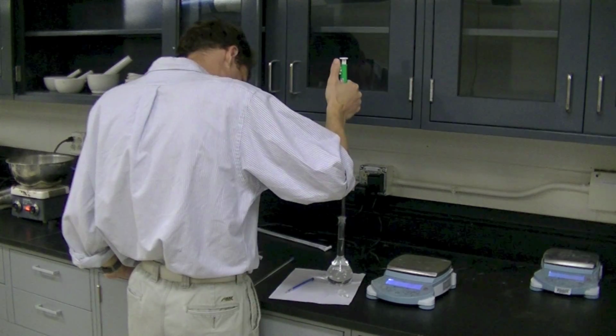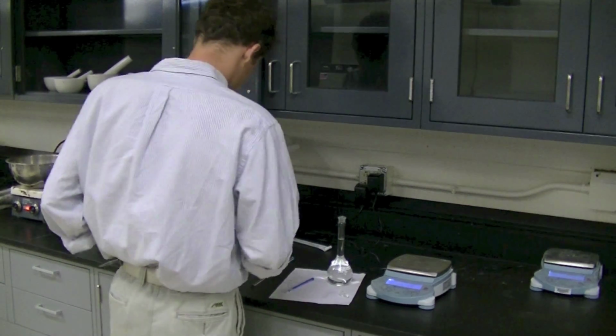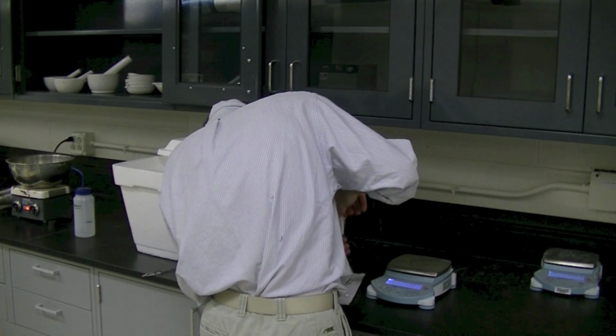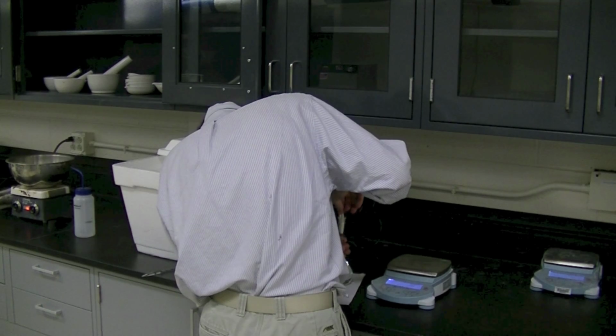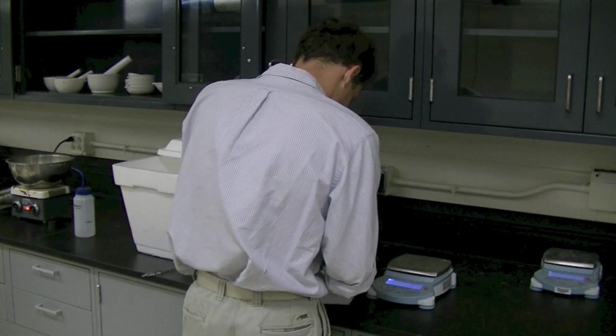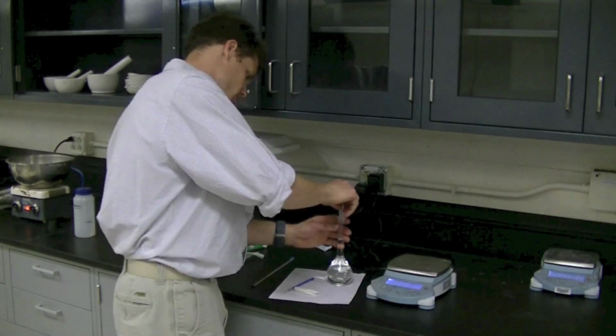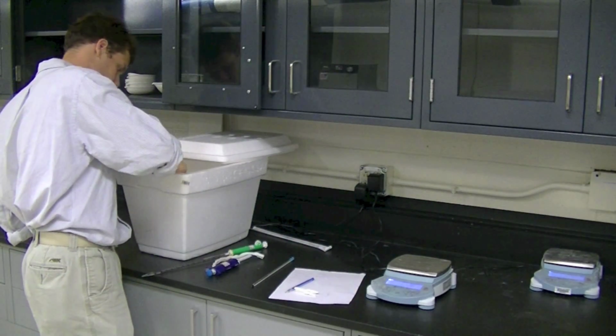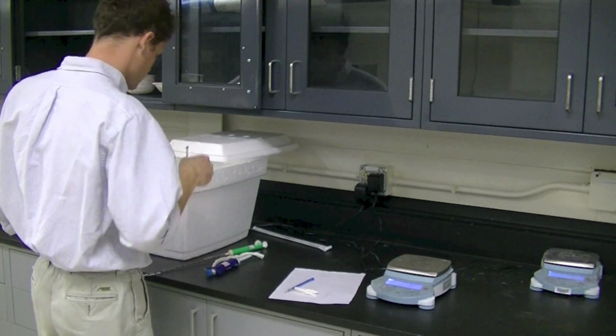Readjust the water level up or down for the next calibration. Place the full pycnometer, thermometer, and extra water inside the insulated container and allow another 3 hours to pass. Thermal equilibrium will again be met. Repeat the process 4 more times for a total of 5 volume measurements.